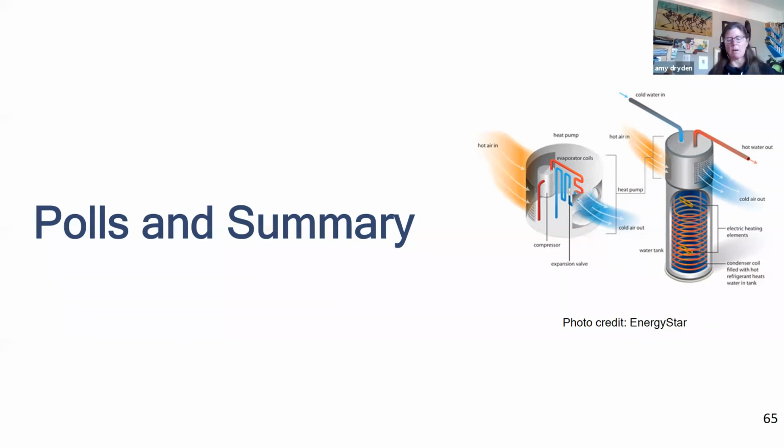A tankless gas water heater is about 84% efficient. And a condensing water heater, you always see the 2 PVC pipe because it's condensing, so you don't have the hot double wall B vent piping. Those are like 92, 94%. So still a lower efficiency.